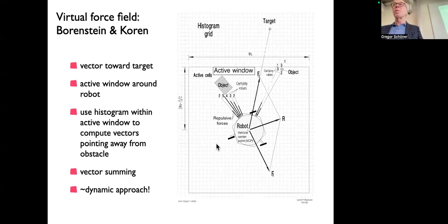So when you have built this little map of the world, now in the world there are some pixels where you have a high probability that there is something there. So you want to avoid that. The notion they had is that from the robot's point of view, in every direction, you add up all the pixels that vote against that direction as a bad direction. This is shown up here as the length of these pointers, and those would be directions that you don't want to go into. So you only want to go into directions where there are very few counts like that.